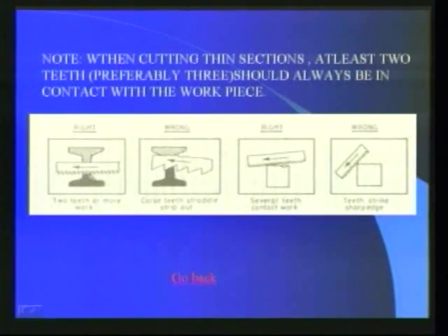Here, a fine blade is used. It is the correct method. Here, if we use a coarse blade, there is a chance to strip out. In this application, this is the right method because more than 2 teeth are in contact with the work. This is the wrong method.